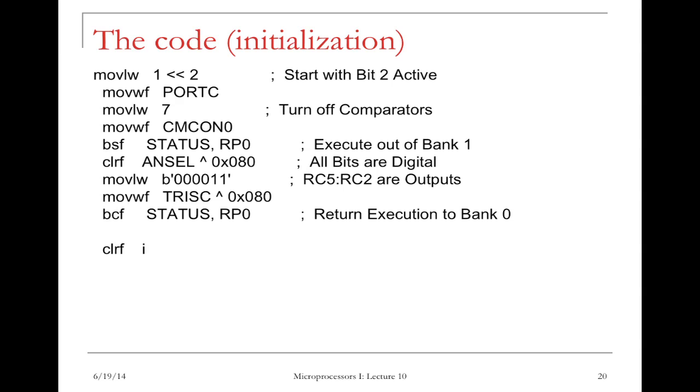This is the PIC, and we have RC5, RC4, RC3, RC2. These are the 4 bits we use to control, to generate the control patterns, the sequences. Remember, when we talk about the controllers, especially for PIC, many of its pins are multiplexed. So these RC pins, they are also used for comparators. So in different application scenarios, you may use these pins to compare the voltage between 2 signals.